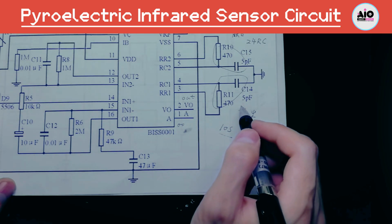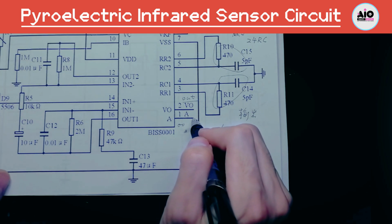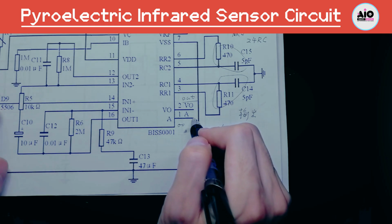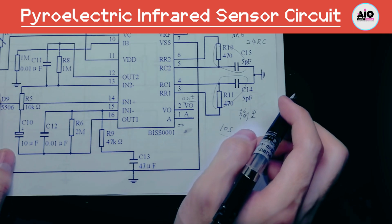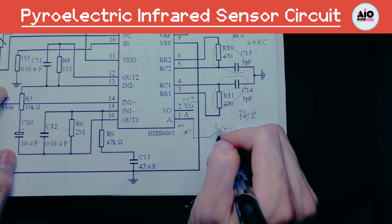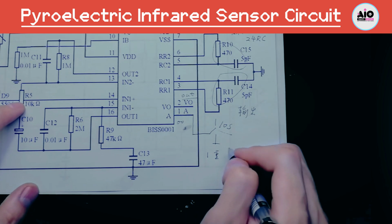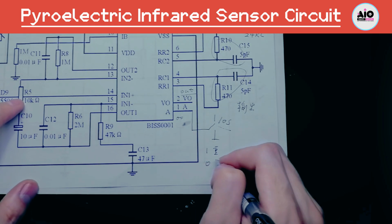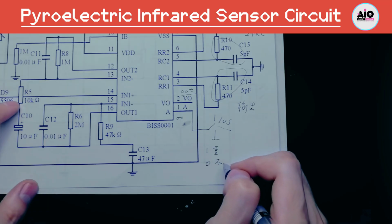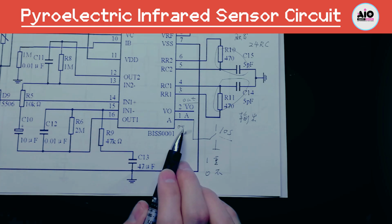Pins 1 and 2 are on the bottom of the chip. Pin 2 is the external output, the OUT end. When triggered, it will become a high level. Pin 1 is a logic control terminal. Its function is to enable repeated triggering. What is repeated triggering? This terminal can be connected to a high level or a low level. When connected to high level 1, it is called repeated triggering. When it is connected to low level 0, repeated triggering is invalid.